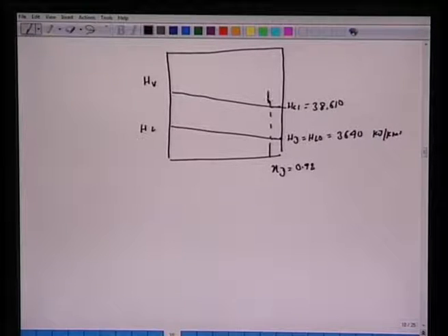So these two points we know, and we have this extended line here. We know the feed composition here at 0.36, corresponding to which we have the enthalpy HF as 2530. All right, so let's find that tie line which is going through this feed.